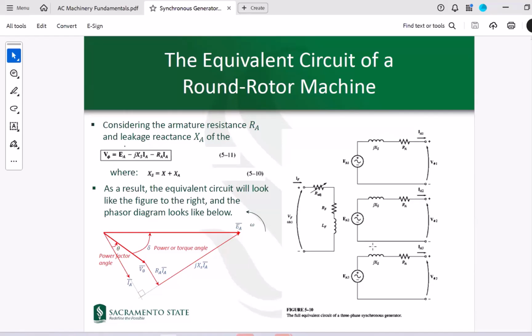How these three phases work, the whole operation is based on the field current. If this field current does not exist, there will be no voltage produced in the machine, right? Vf generates If. Vf is provided to your exciter to generate If. So it's also important to acknowledge the existence of this excitation circuit, which is coupled with your armature.